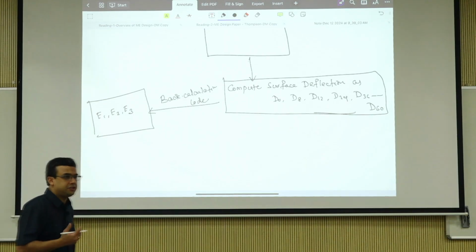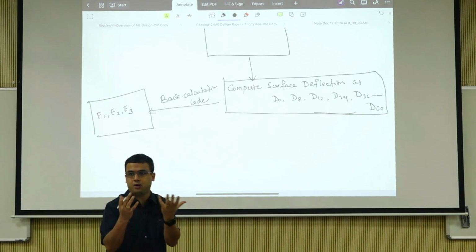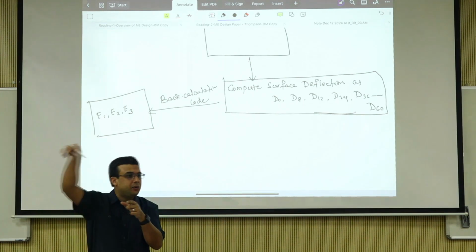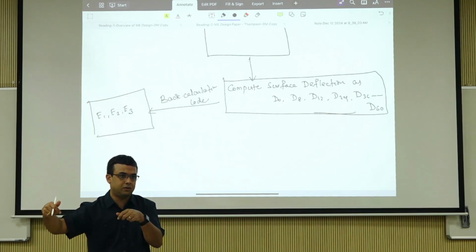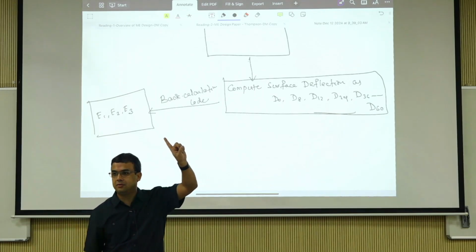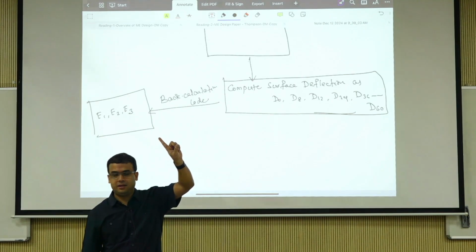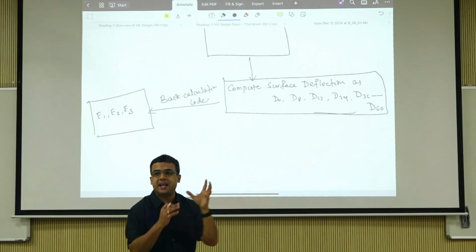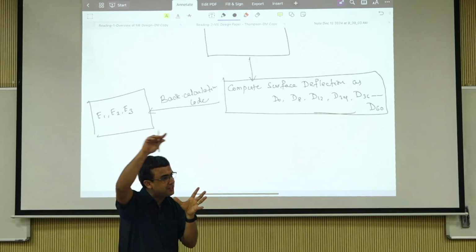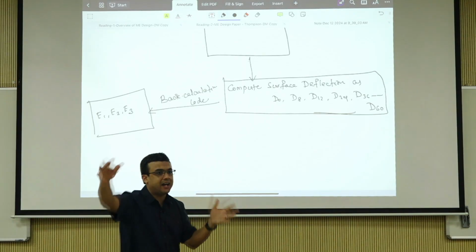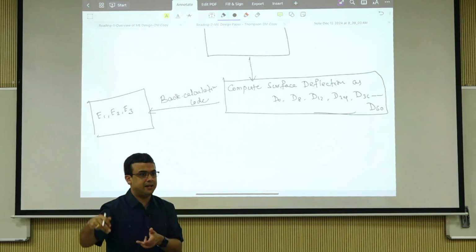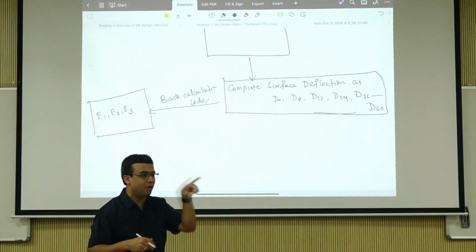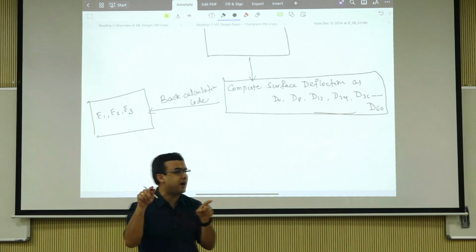Do you see what I just did? I took a stress dependent modulus model, I predicted surface deflections, and I fed it into an FWD algorithm or back calculation algorithm, and now I ended up with one modulus, E2. So that E2 is representative of the entire stress dependent behavior of the entire layer, because that is what you fed into it, right? So this is kind of a cheating or a way around, not cheating, this is kind of a smarter way.